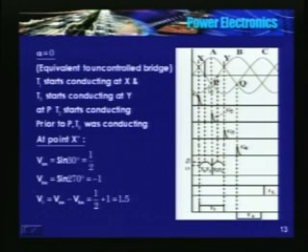Just prior to P, VAN is at the peak, approximately sin 89 or so, which is approximately equal to 1, whereas phase B is at 330 minus, that is again minus half. So VAN is 1, VBN is minus half. So output voltage is VAN minus VBN, it is again 1.5.